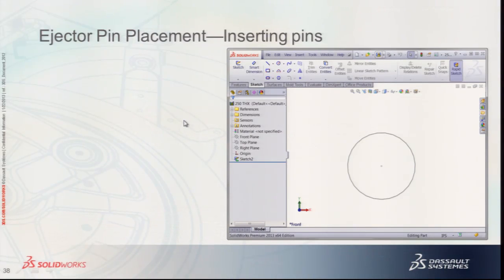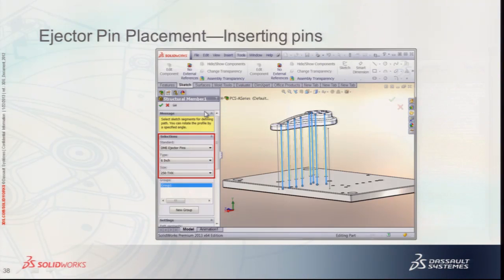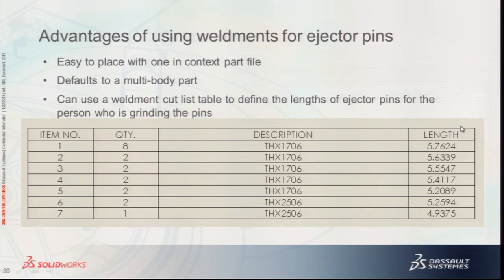It's there on the menu here. Right here, you'll see it, and you'll have a whole set of options based on how you have that set up. But the advantage to having that is weldments give you a length, and so if you pull it out enough decimal points, you can get a pretty accurate measurement, assuming your mold stacks up in real life based on your CAD model. And so you have basic lengths, and I've actually added a formula in some cases where it takes it from the parting line.